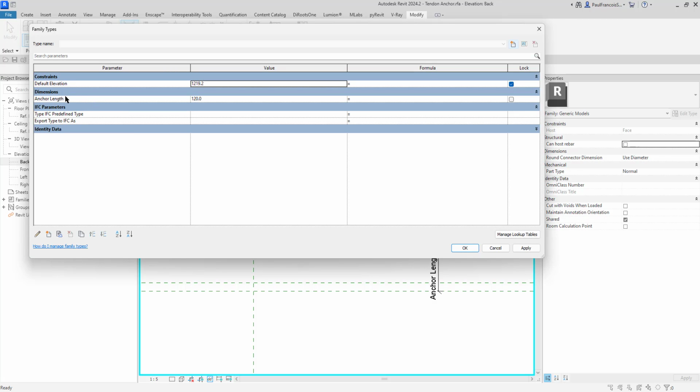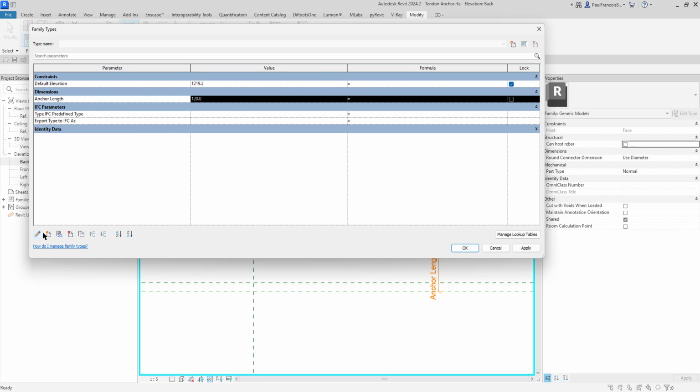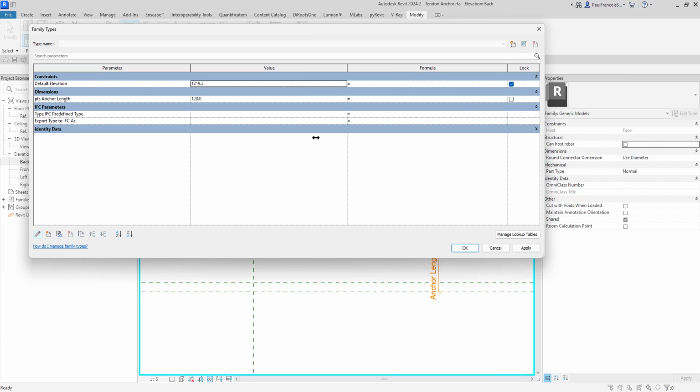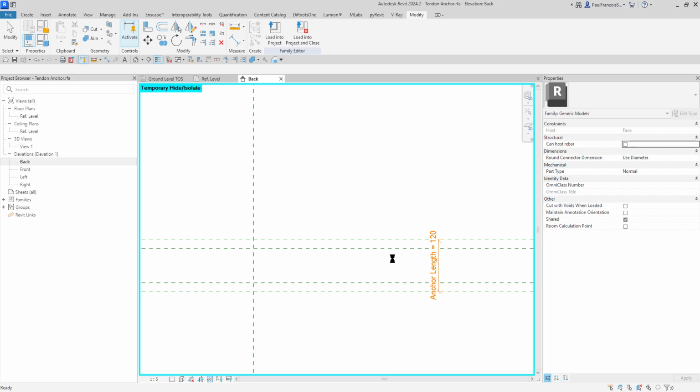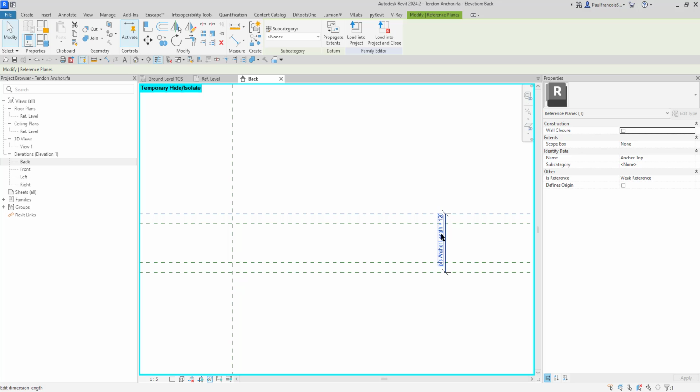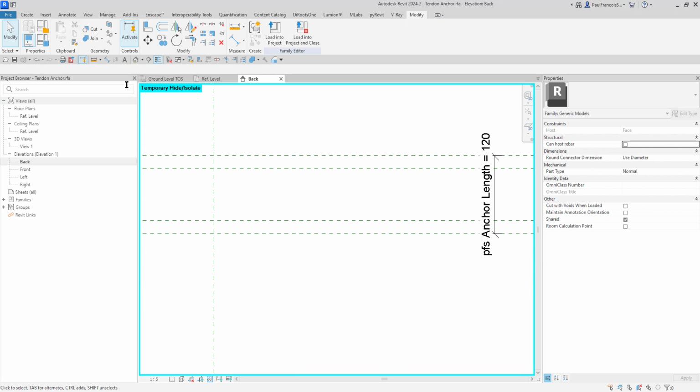For good measure, what you could also do is just to differentiate. You could always edit that parameter afterwards, and I'm just going to put in there my initials PFS. That will just identify my parameters to me. It's 120. And to drive the geometry, if you wanted to change that, you could do that to 130 or back to 120, just as you wish. Right, so we're basically creating a flexible family over here.